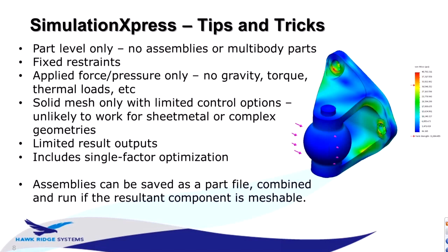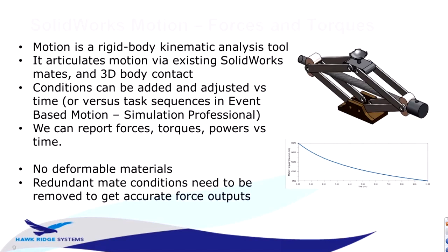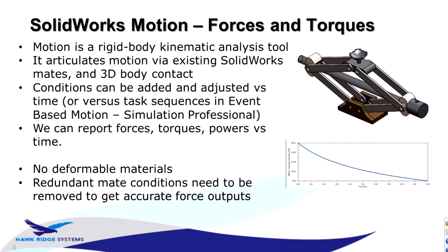Okay. Now, next thing we get a lot of questions on is SOLIDWORKS Motion. Okay, SOLIDWORKS Motion is included as part of SOLIDWORKS Premium, and it's also included if you purchase any simulation package, Simulation Professional, Simulation Premium, the main two. And what SOLIDWORKS Motion is, it's a way to extend the general kind of articulation and movement that is inherent in SOLIDWORKS, you're developing assemblies, and add real data behind that, right? Add forces and torques and pull results off it.